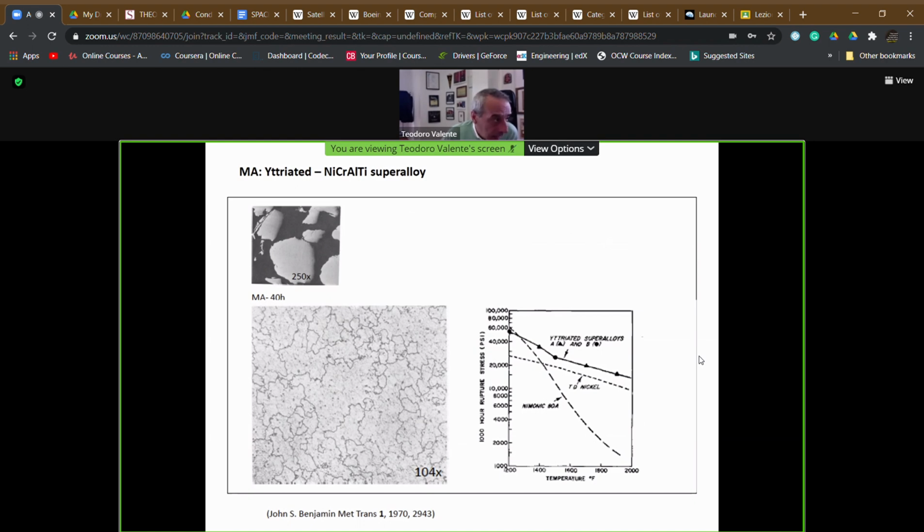So at a glance, speaking in terms of the sum of these two phenomena, today the nickel-based known superalloys still have a better creep resistance than the ODS materials, because we can act on both creep phenomena, diffusion and dislocation-based creep. With the ODS materials, instead, we can just act against dislocation creep, but not against diffusion creep.